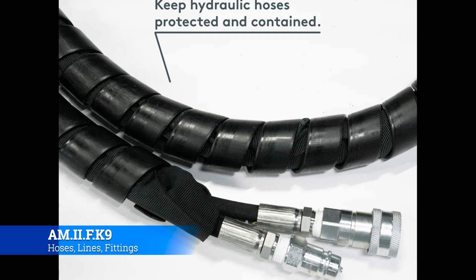What we realized is that we had seen the snake skin and thought the line was okay, and what it actually did was hide a hose that was starting to fall apart underneath it. Whenever you inspected it, if you didn't pull the entire snake skin off and look at it, you would have never seen the hose degradation underneath.